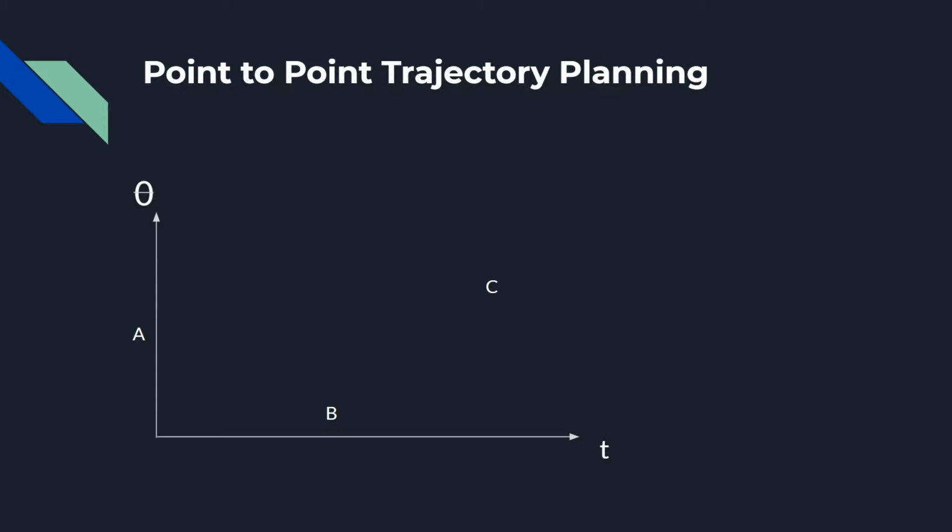So trajectory planning, it could be linear, where we just went from point A to point B to point C just by changing the value of theta linearly. Now we saw that if theta changes linearly, the final output would not actually be a linear end effector velocity. The end effector's trajectory would not be a straight line necessarily. As we saw in our example, the end effector was actually pretty much going in a curved manner. And we'll see that again today because a bit of this had gotten cut off while we went through it. So this could be one way of point to point.